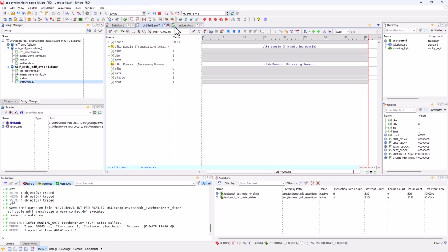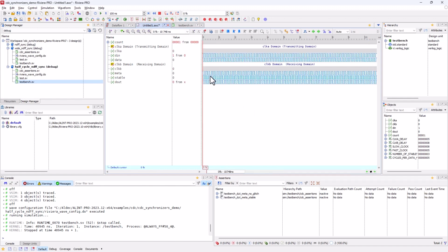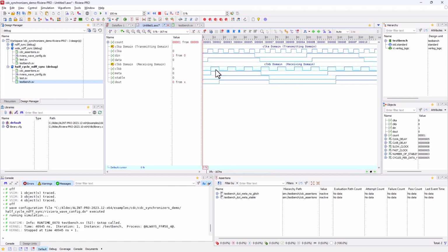Essentially everything works exactly the same in this test bench, and so we get a very similar picture in terms of the waveform. If we go over to the beginning, the only real difference is that if we take a look at the time it takes from D_N going to the output, which is going to be over here stable, we'll notice that it only takes 1 and then 2 clock cycles, or rather 1 or 2 transitions. Because instead of having to go through 2 full flip-flops, where each reads in on the positive edge, we instead read in on the positive and the negative edge. So the first is the positive, then the second is the negative, and that means it can go through twice as quickly. So that's the main difference here.